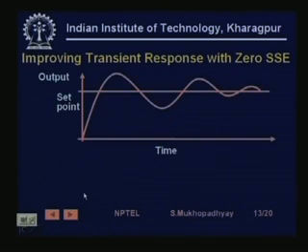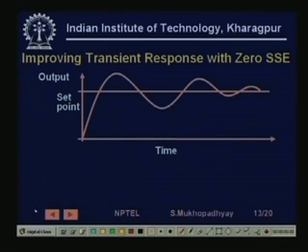If we want to do that, then what we have to do is, around this point, keep braking so that we can quickly turn. Here we have to slow down. Slowing down means during this phase we have to create more negative input, which will grow towards this point.